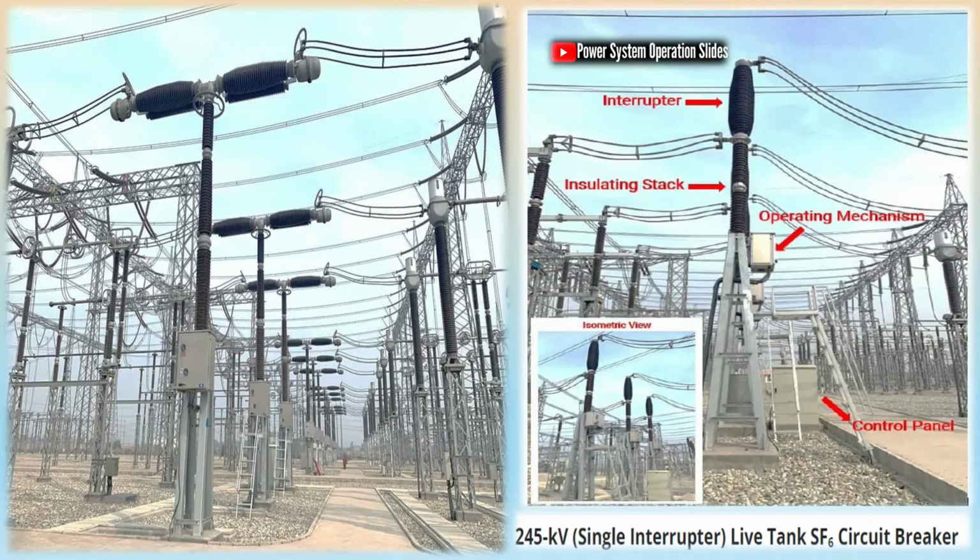As the downward movement continues, the main contacts separate and the current commutates to the arcing contacts, which are still in the closed position due to their physically longer construction. During the course of further opening, the arcing contacts start to separate and an arc is established between them.